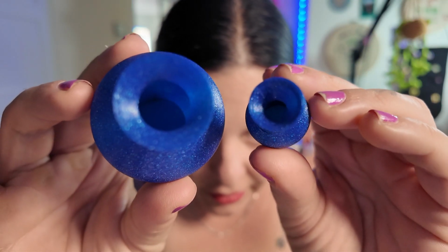Yes, so one tip that I wanted to share is, if you want an actual vase more resistant, then you can increase the wall thickness. So you can select the vase spiral mode and then you change the wall thickness, so you have 2 perimeters, and it will make the object much more resistant. Printed with different wall thickness, this has 2 wall perimeters, this has only 1.